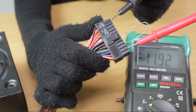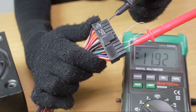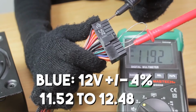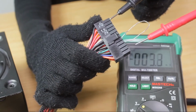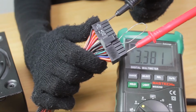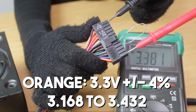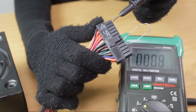Now the blue is giving me negative 11.92. My chart says it should be about negative 12. That's perfect. So the range here is going to be 11.52 to 12.48. And last is the orange, and we're getting a reading of 3.381, and the range should be between 3.168 to 3.432, because this is a 3.3 volt test. So perfect. So this side everything is okay.